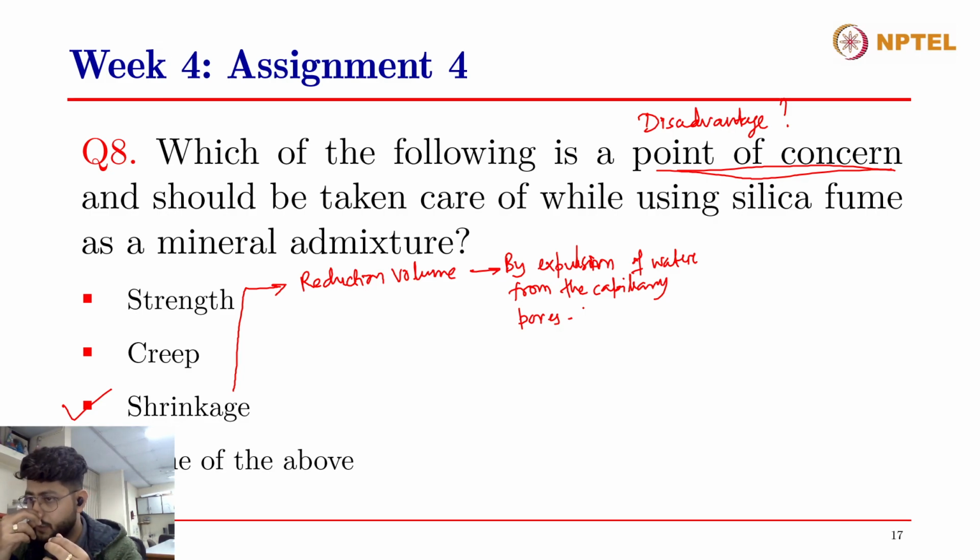Or in case of plastic shrinkage also, it rises up to the surface and there is a subsidence of the total volume, and this water gets evaporated into the atmosphere. So shrinkage is basically reduction in volume caused by the expulsion of water from the capillary pores.